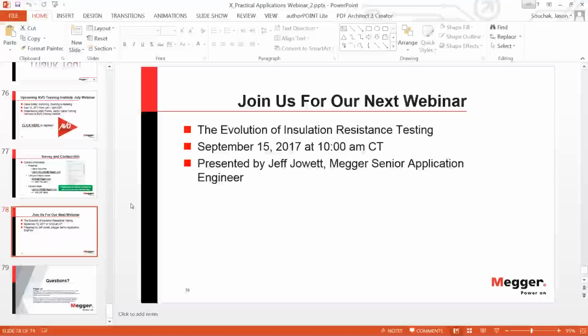It can only show you the global aging condition. So if you had a fully grown water tree that I think Jason was referring to, one of those water trees that has almost crossed the entire insulation, it just takes one voltage spike and the cable will blow. So the tan delta will not show you that one spot, okay? So it's always a good practice to do that.